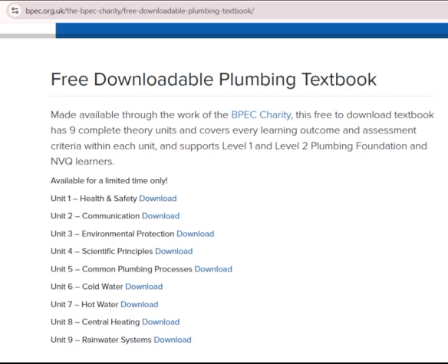The pressure gauge. This shows the pressure within the system. It should also be installed on the heating return pipe, close to the expansion vessel. The pressure relief valve. This component, also known as the expansion relief valve, should be installed close to the expansion vessel. It is a spring-operated valve that provides a safety release of water and pressure. Should the expansion vessel malfunction, most pressure relief valves are set to operate at 3.5 bar.